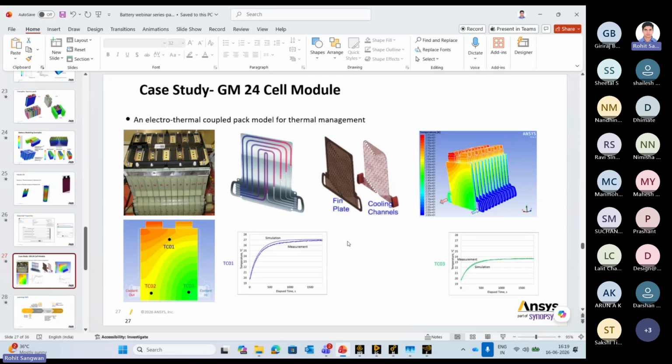Okay, how we are doing the meshing matters. If we change the mesh, the result will also change. So for that we do a grid independent study, but the pattern should come out the same way. If there is a sudden spike, we should also get the sudden spike.